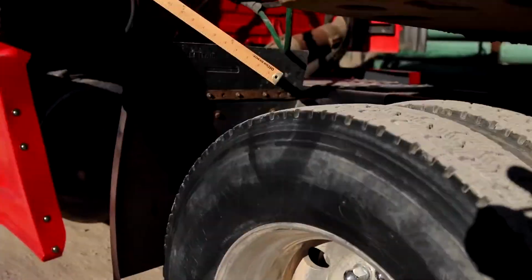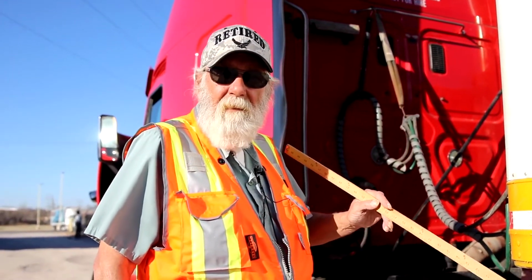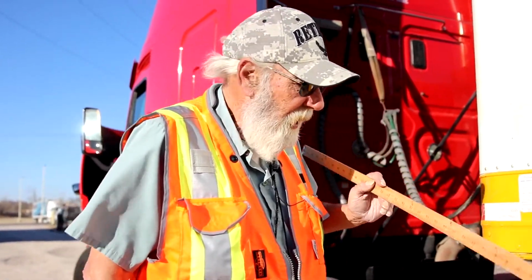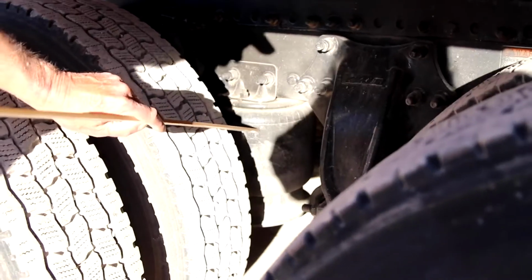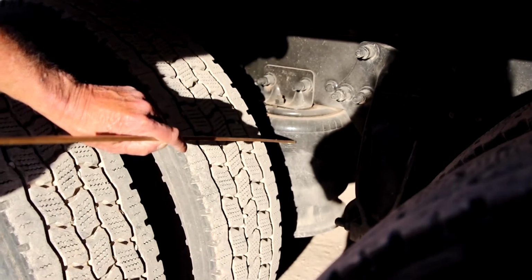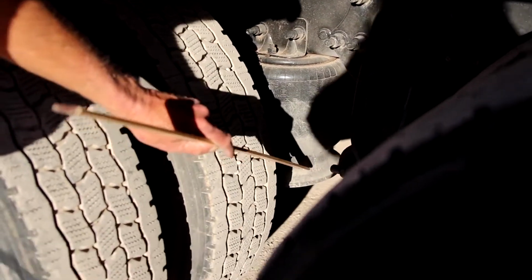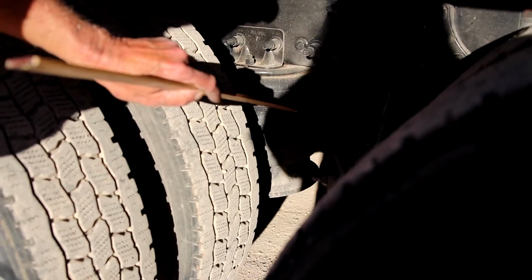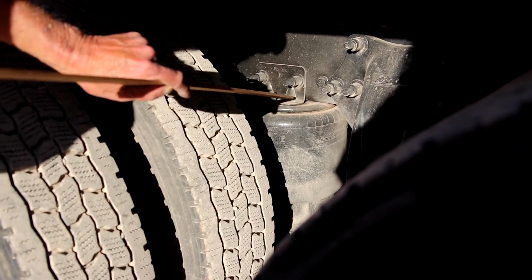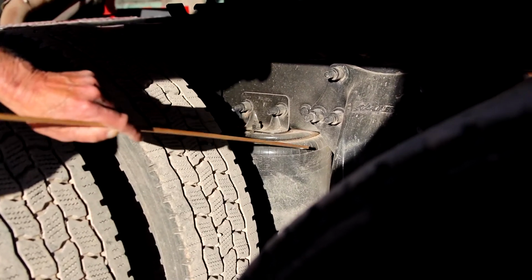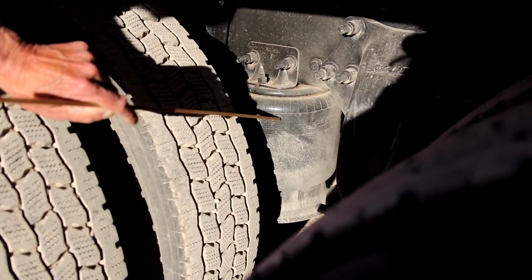I would check the other axles as I've done this one. That is it, almost it for section B. This truck also has airbags for the rear suspension. It has an upper and lower airbag mount, and it's filled with air, so you're listening for leaks. Mounted securely to the vehicle, not damaged or broken. The bag has no abrasion, bulges, or cuts.